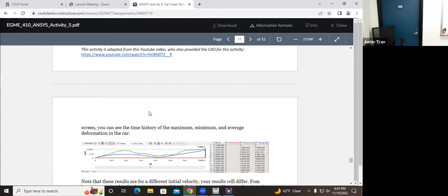You're just going to define the matrices. You're going to make a 4x4 matrix and set the entries equal to this one. So you're going to make this 4x4 in MATLAB, and this 4x1 vector in MATLAB, and then do matrix backslash the vector, and that's going to give you your answer. It's going to give the deformation, and that's the D vector.